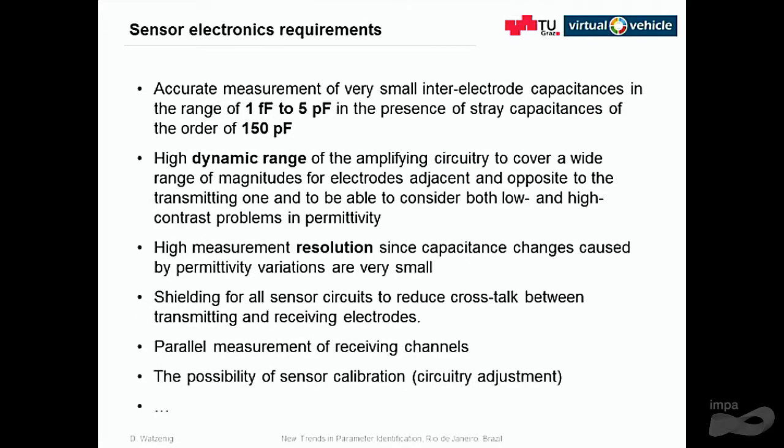If we, let's say, first have a step before we talk about the maths behind, about the equipment, because I would like to motivate it from the application side. We basically need to measure the voltage around our pipe from the different electrodes, which are typically 12 up to 16 electrodes. That's quite common sense. Meanwhile, we have to put quite a lot of constraints and requirements on our electronics.